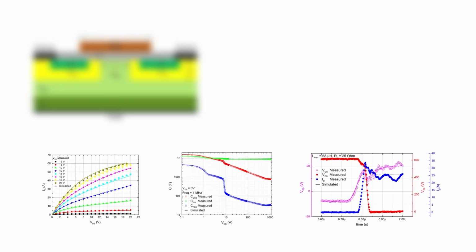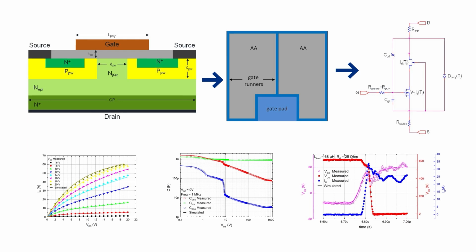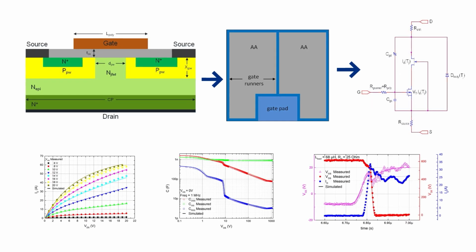But for onsemi's silicon carbide parts, they do things a little differently from other companies. Typically, when component manufacturers, and not just transistor makers, create models for their parts, they do it by measuring a small number of actual components in a small number of cases. Then they build a math model based on that limited data set. The SiC models from onsemi are based on the physical device's topology and packaging parasitics. The result is what they call a scalable model.